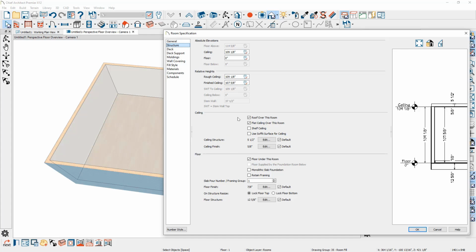If you're an interior designer and you just want to use a finished ceiling height, you could very easily type in 108, 96, or 120 and set that as your template plan default, and that way you just have nice round dimensions. If you're a builder and you care about framing and you want to get exact stud lengths, we usually have those dimensions set for you. In these dialogs you can also use math. If you wanted to add 12 inches, you could say plus 12 or minus 12 inside the dialog, and you can actually do dimensions inside of that dialog.